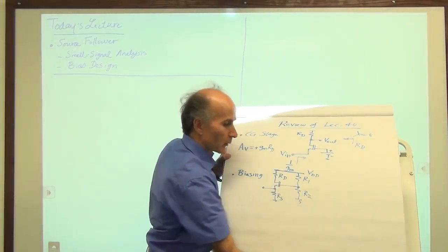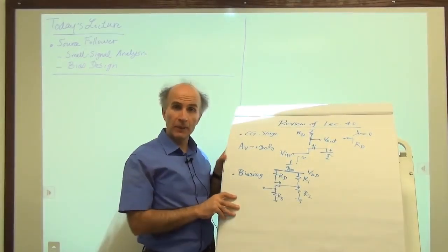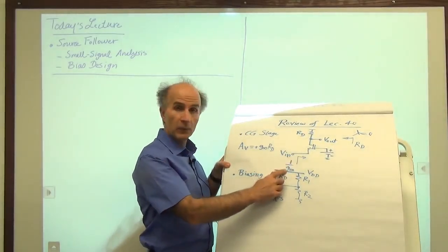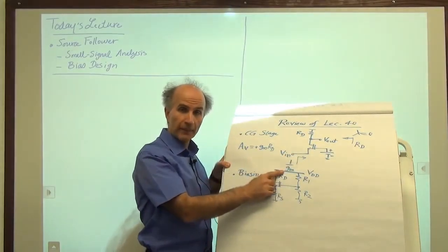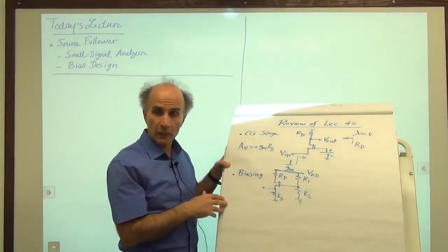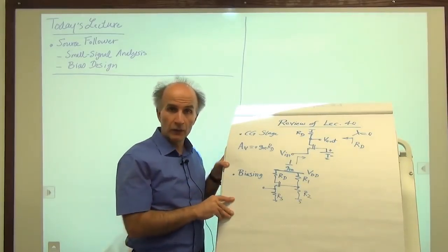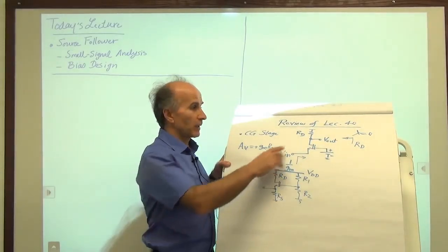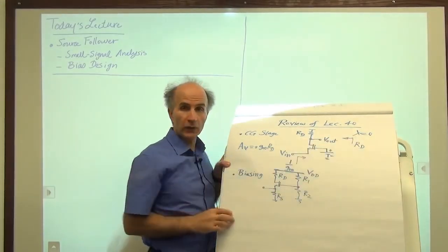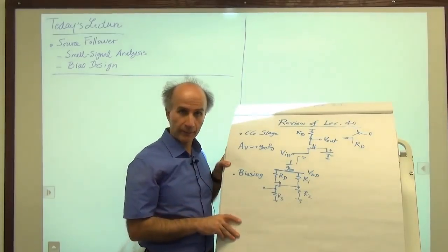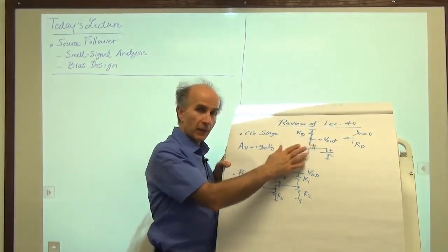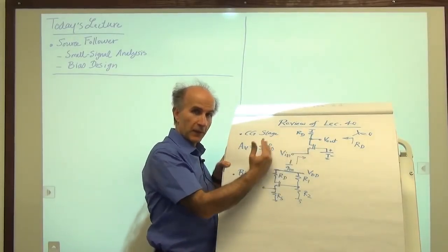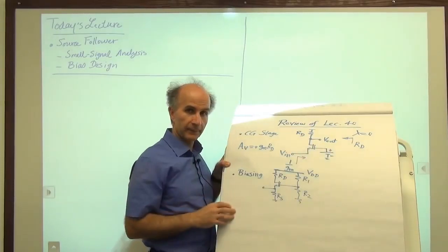Okay, and then we also found the input and output impedances of the circuit. And we saw that the input impedance is about 1 over Gm. We say looking into the input, we see 1 over Gm. And it's a relatively low value. And we saw that perhaps it could be used to match the impedance of an antenna, as an example. And the output impedance, if lambda equals 0, is equal to Rd. Well, that's something to remember. The input and output impedances become important when we interface the circuit with other circuits preceding it or following it.